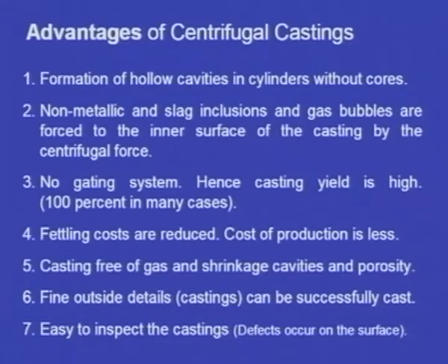Now let us see the advantages of the centrifugal casting process. Formation of hollow cavities without cores. In the case of the conventional sand casting process, if we have to make a casting with some hole, we have to use a core, and to make that core we have to put in extra effort.